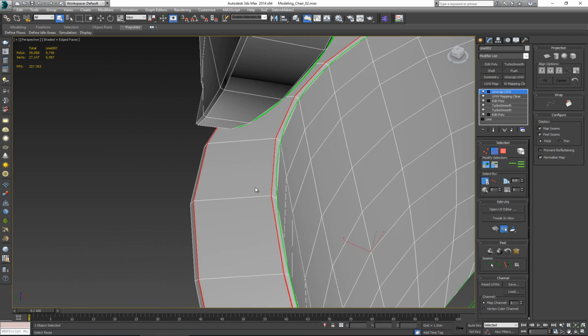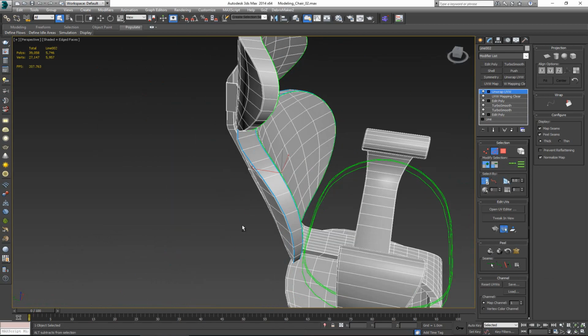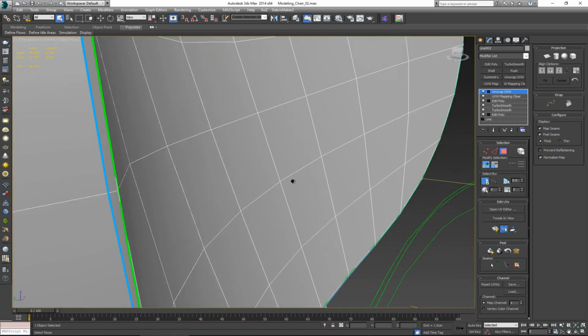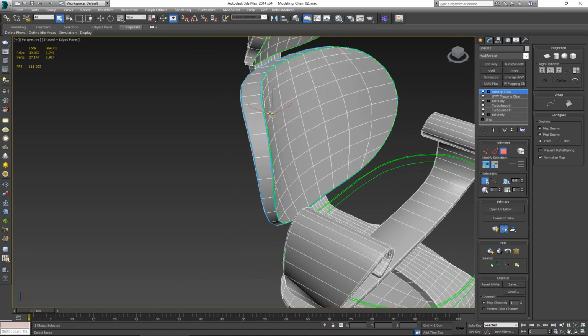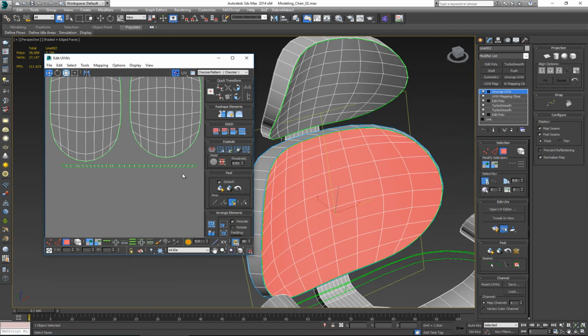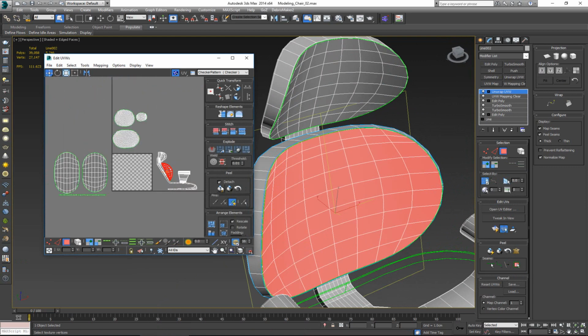So again, loop, convert to an edge, find a hidden place like this one, and convert this thing to a seam. Double click until you get this thing here. There we go. Open the UV editor, and do the same thing with the peel. Move it to the side.